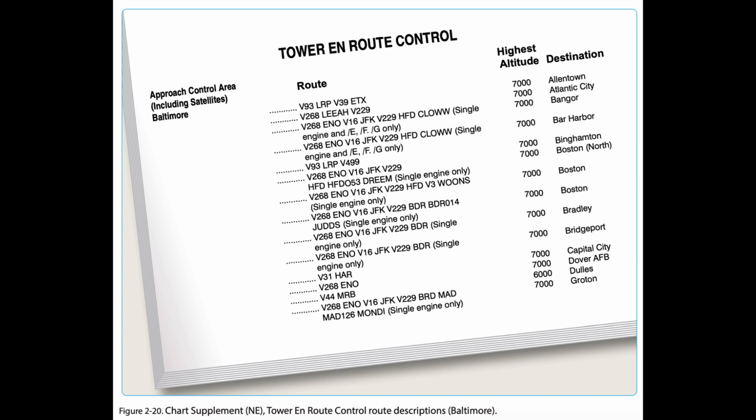When flight planning, it is important to always check current publications for information about the departure and destination airport. Routes are effective only during each respective terminal facility's normal operating hours. Always check NOTAMs to ensure that appropriate terminal facilities are operating for the planned flight time. Altitudes are always listed in thousands of feet.